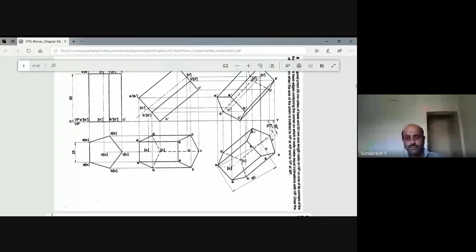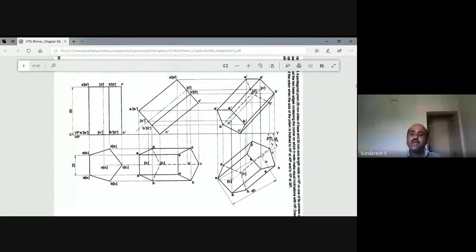This is the furthest point in this front view, furthest point from the observer. So that is point D. The simple way, again the same as I explained for the initial top view: the edges which come out of that point should be considered as invisible edges. See here, DE is one edge, DC is another edge, and of course D1. D1, DC, DE, these three edges are not visible in the front view.